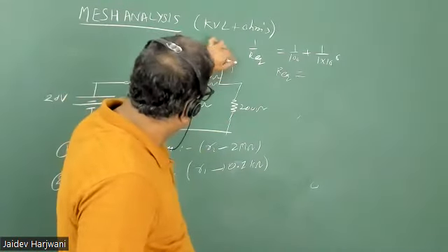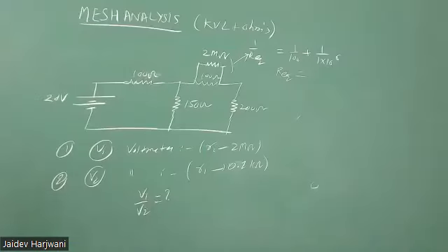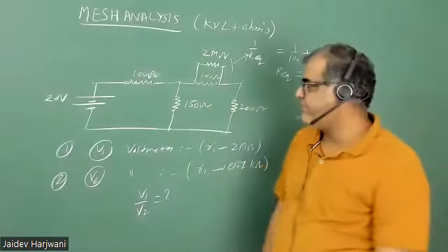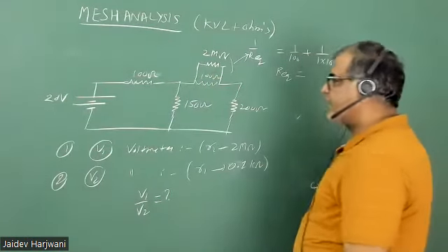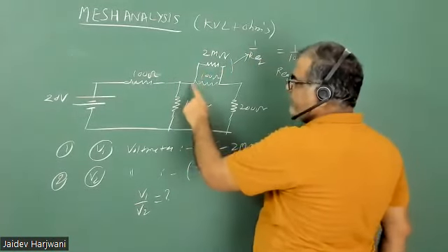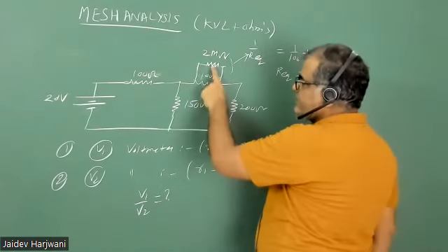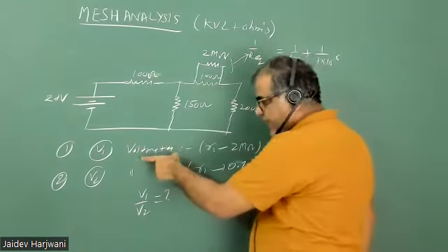I'm taking the equivalent of these two. What is the value of R equivalent? It will be approximately equal to what? See, 1 by 100 and 1 by 10 raised to power 6, so approximately 100. That's what I'm trying to say. When you have a high resistance voltmeter, it will not affect the resistance of the circuit. That's why we always use a voltmeter with a high internal resistance. So if you put the voltmeter here, it will give you the accurate voltage. It will not consume any current, so it is not affecting the resistance of the circuit. This is the ideal voltmeter.